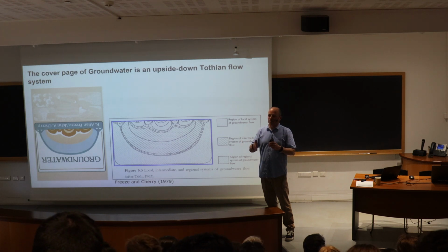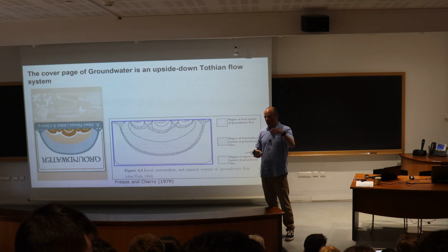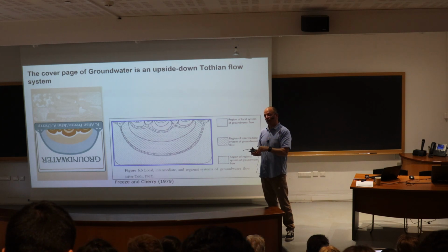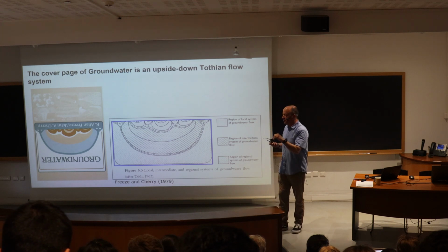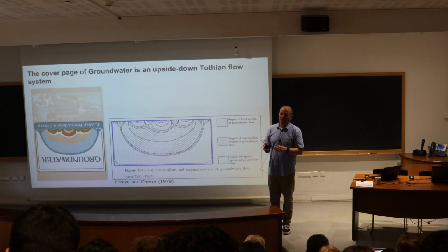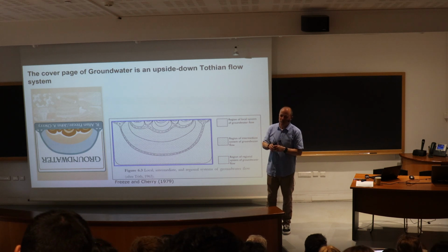I have to use a lower porosity, and then this concept of dead-end pores would play, because in your material you might have some pores that are better connected, conduct more flow. The tracer will preferentially migrate through these pores, and the tracer will go into the dead-end pores and not. But actually, the breakthrough curves would show other signs as well of that.